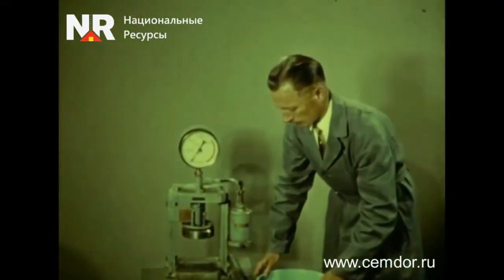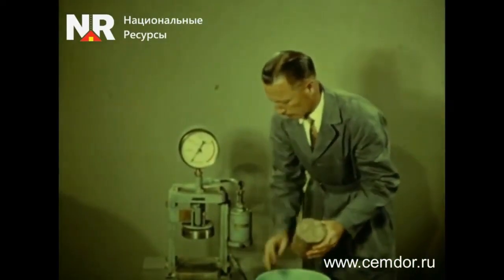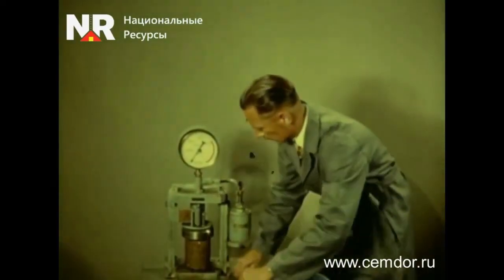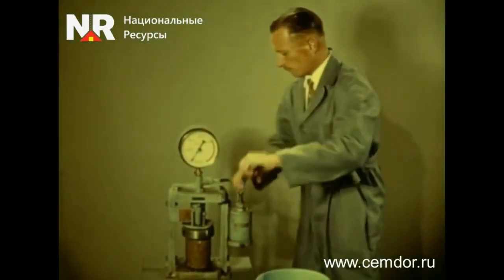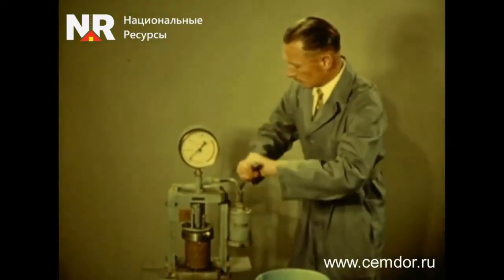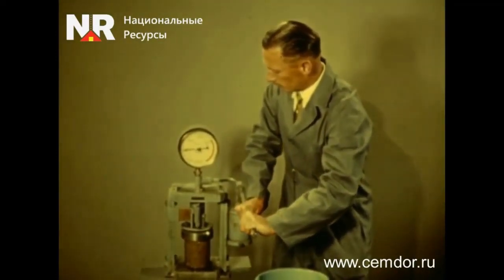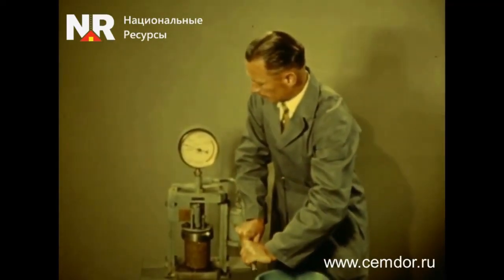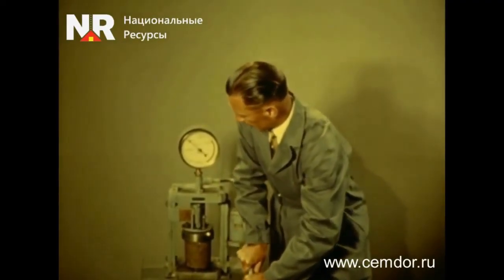The resulting samples are stored in airtight packaging for a period of 7 days. After the specified curing period, the samples are removed and their compressive strength is determined using a hydraulic press. The results of these tests determine the required cement content to achieve the specified strength parameters. In practice, the strength characteristics of soil cement are the basis for calculating the entire road pavement structure. At the same time, low soil strength may indicate the presence of various impurities in the original soil composition which hinder the hydration of cement.